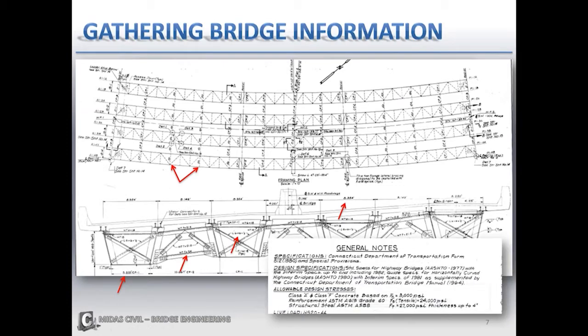Then from your general notes, you're going to want to get your material properties. So you're going to want to go in and grab the type of concrete that was used, the reinforcement and the steel, and all of the strengths that are assigned to them.